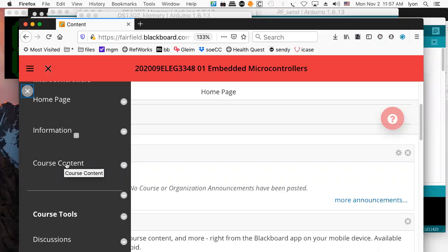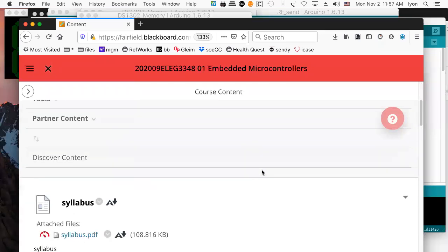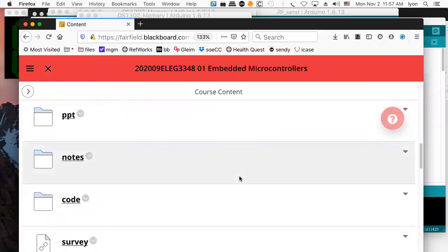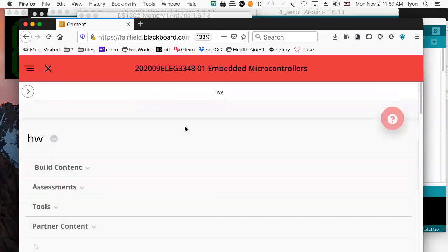And third, my plan is to use the NRF24L01 radios in order to be able to do serial data communications. So we're going to have a nice RF lab, that is a radio frequency lab at 2.4 gigahertz using the ISM, or Industrial Scientific Medical band, which is kind of halfway up on your microwave oven's dial or something like this. It's kind of an interesting thing. It's unlicensed. You can have your own little radio. You can broadcast to all the other little radios. And in fact, that's great fun.